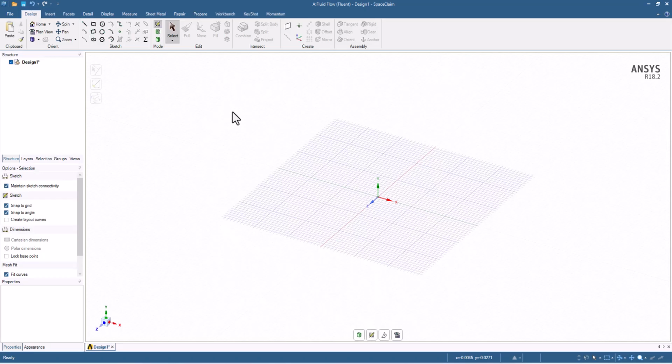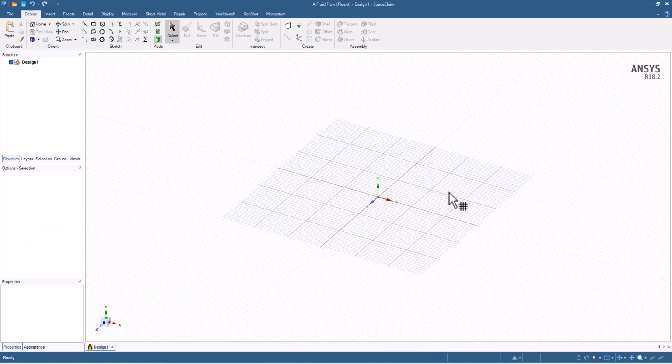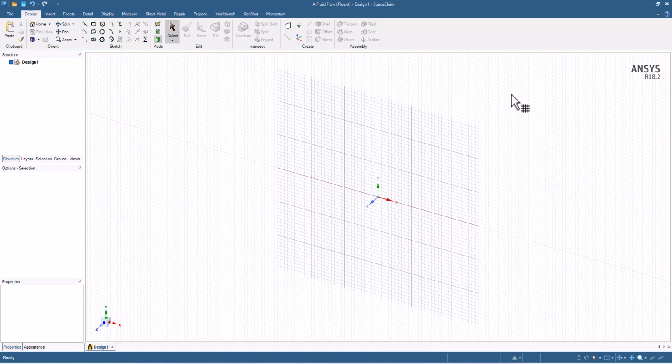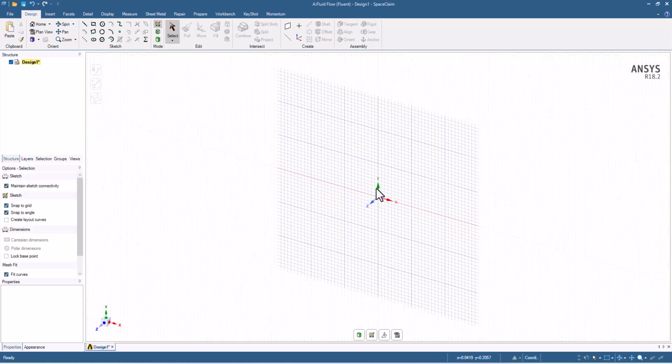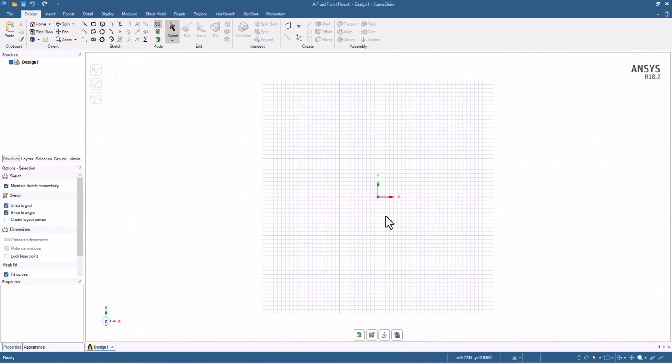After that we have to activate the equation option from here. Under Sketching, click on Sketch New Plane and click here on the extreme right side, so that the sketching plane is basically an XY plane, and click on Plane View, and the plane view will be at the front.